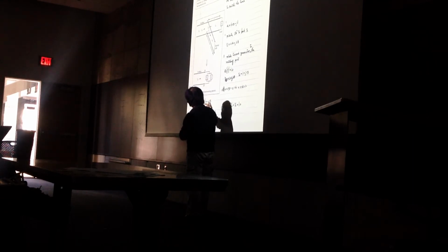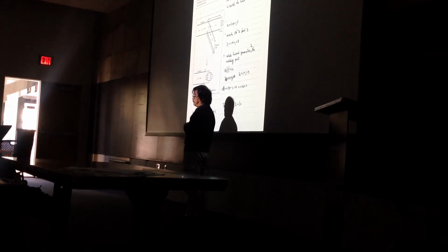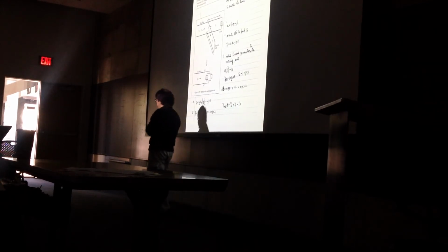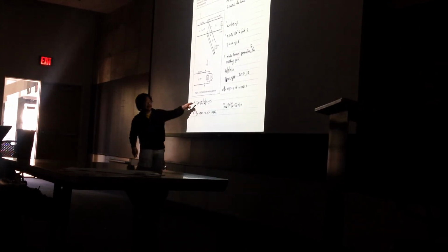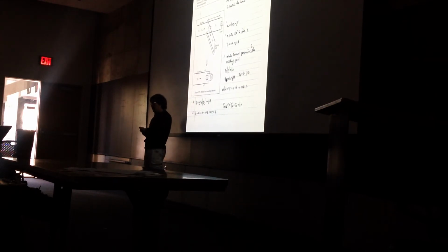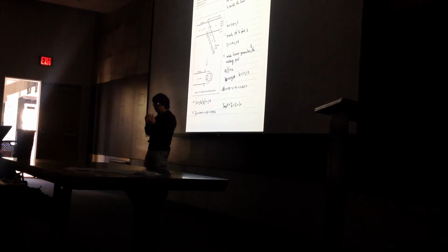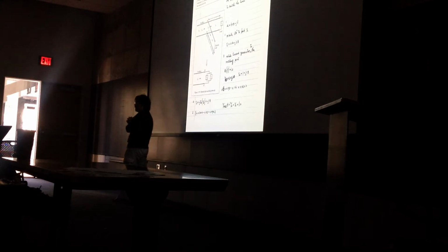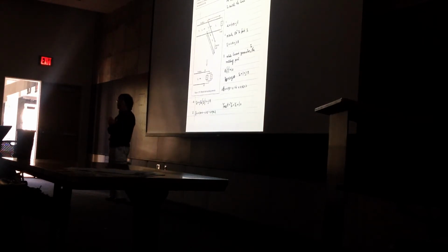You need to provide a minus 1.5 kind of admittance in order to cancel it out. Okay? So you need to provide this 1.5 admittance to cancel it out. And then here's the question: how to provide a parallel connection which provides you the minus j1.5 admittance?